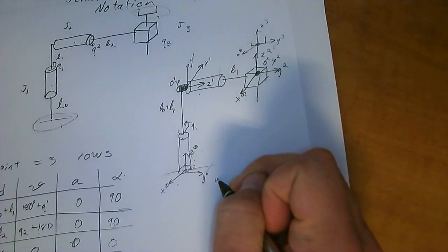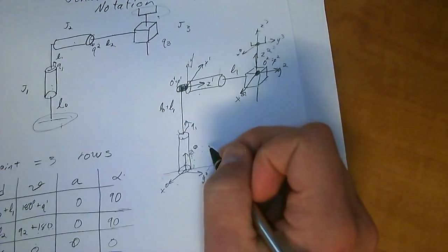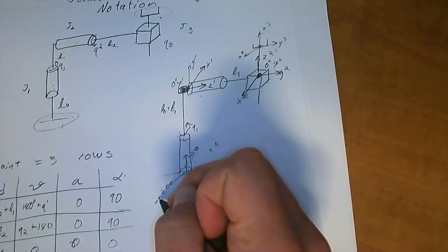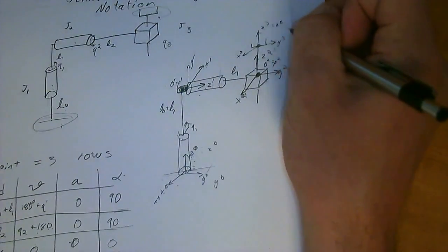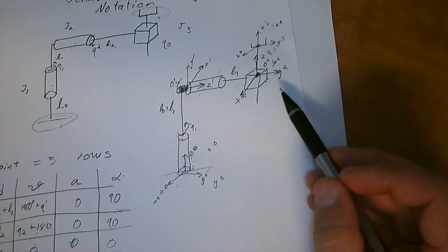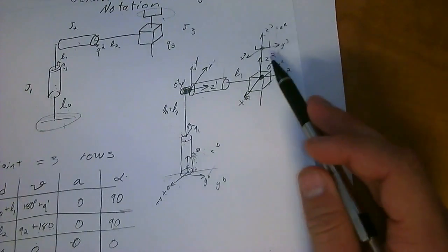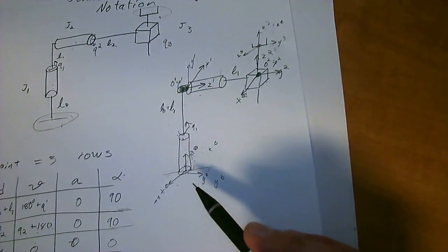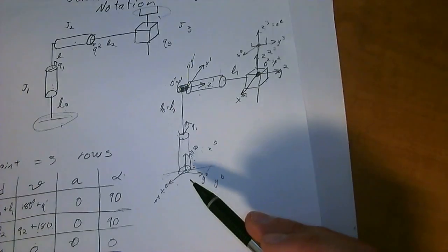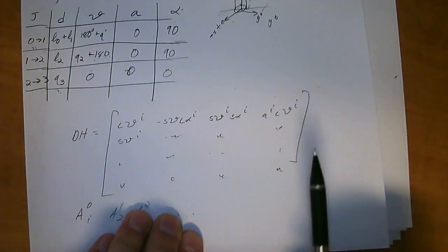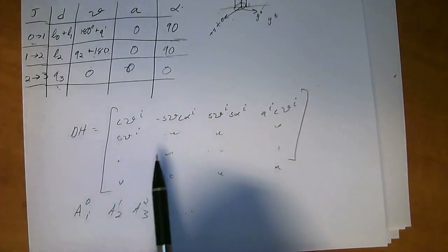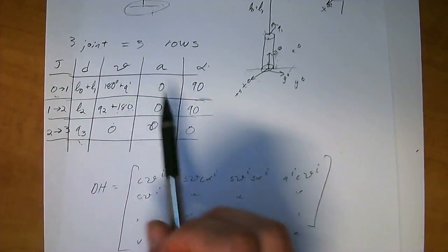But in this case, this would also equal y base, z base, x base, and so on. And then this one would also equal ze, and so on. And then you would define the rotational and translational matrices about those. They would end up being identity matrices most of the time. And then from there, you can solve this entire actuator system. So that's the equation you need to use if you want to go any further than that, but this is your basic DH table.